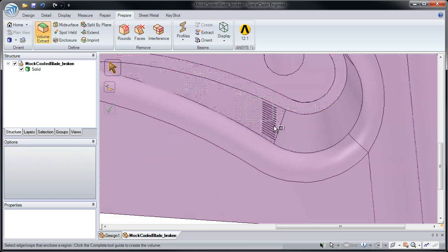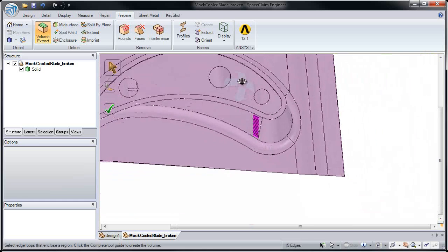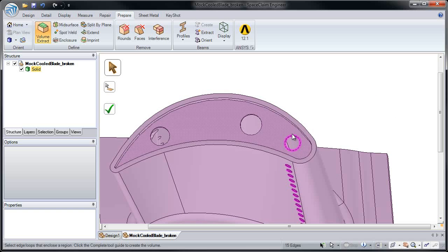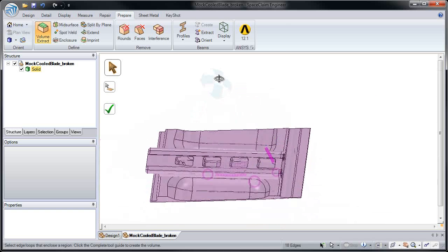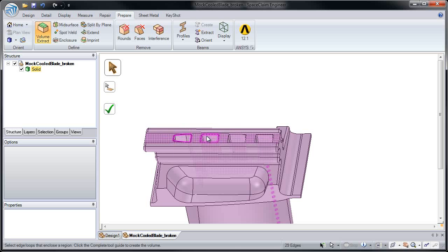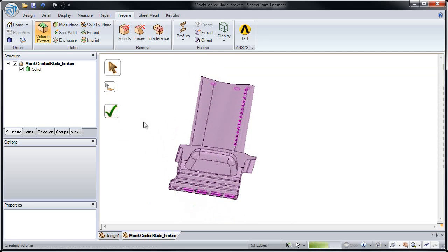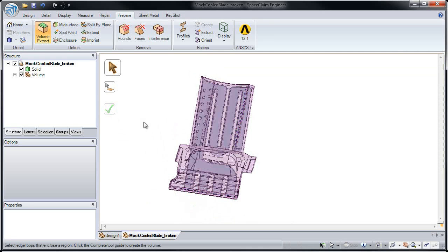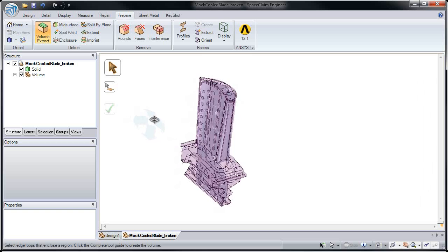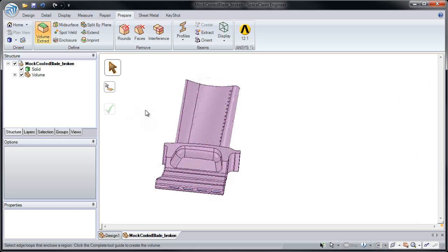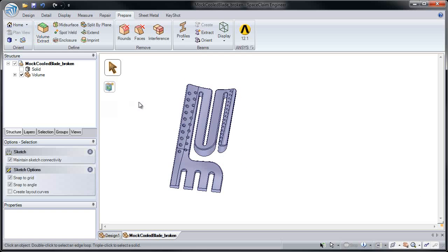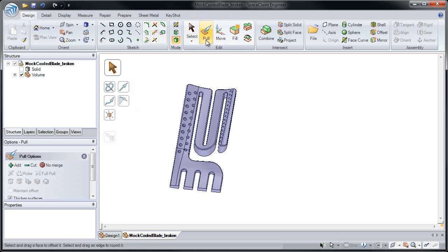If we're worried about the fluid flow running through this, we'll make a volume extraction of it, so then we can test the heat as it's going through. And we can do this by identifying all the inlets and outlets that are there. So instead of having to do complicated cuts and new feature adds in its originating program, we can easily create the geometry needed for analysis inside of SpaceClaim. So now we have the outer solid and that inner fluid volume.